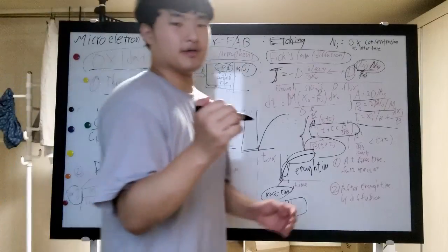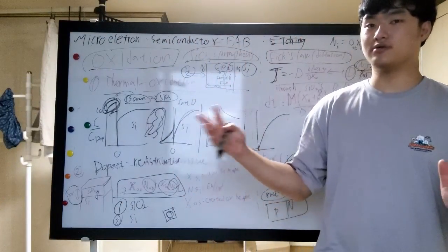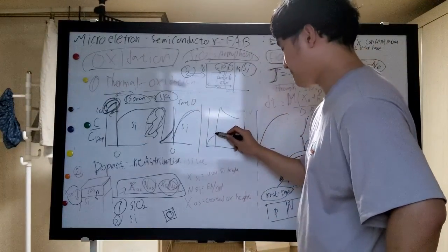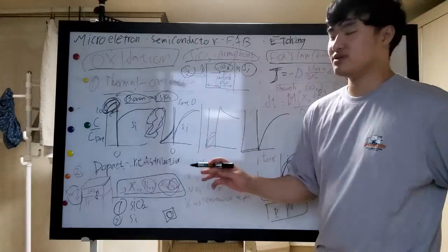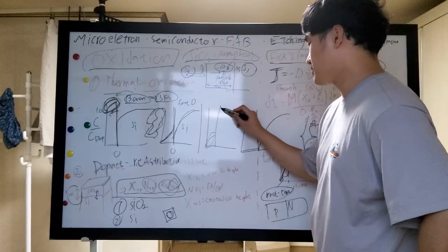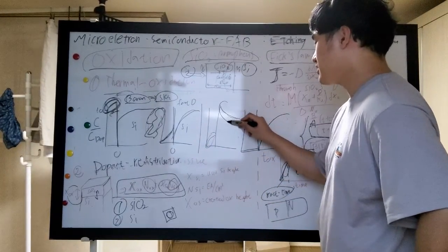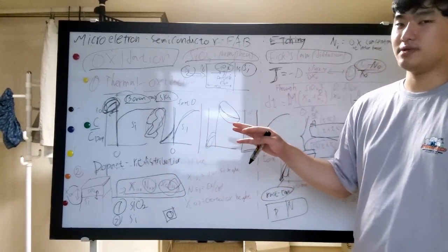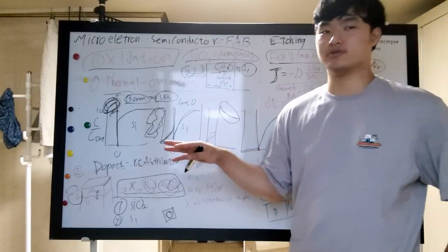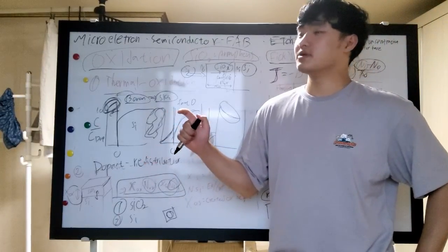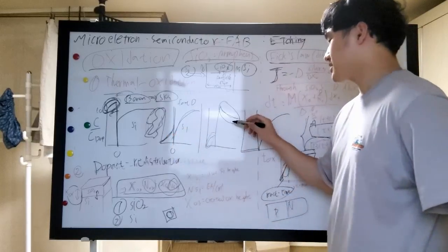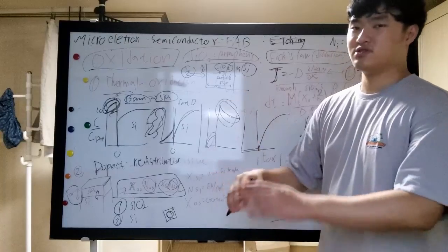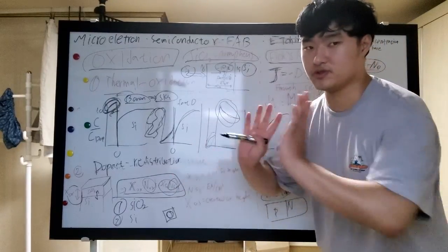And secondly, if the dopant has moved to or stays in the silicon. Here, first, its diffusion coefficient is somewhat low, and the dopant will stay on the silicon side. Surely, at the interface, the silicon surface will have a higher boron concentration than the dioxide side. Of course, it means the boron will not move to the dioxide side. Only a small amount of the dopant will move to the dioxide side.